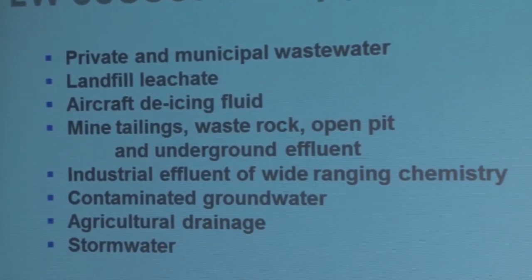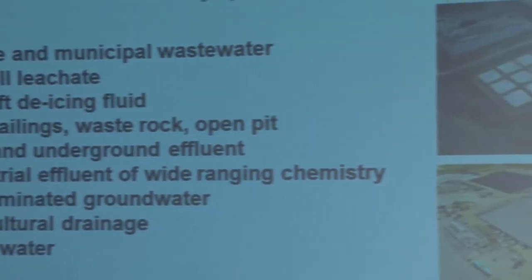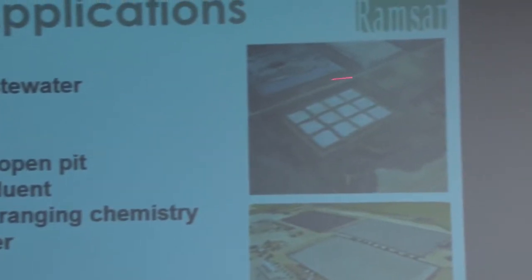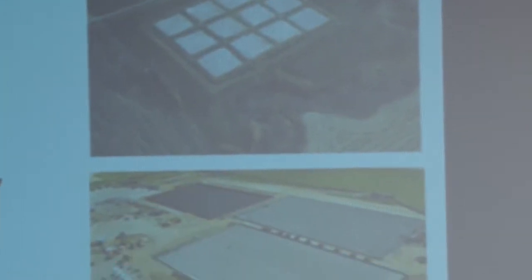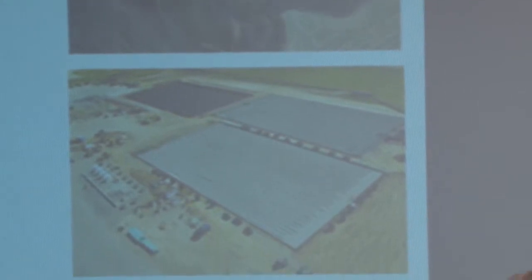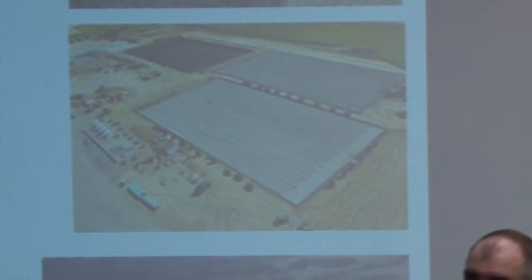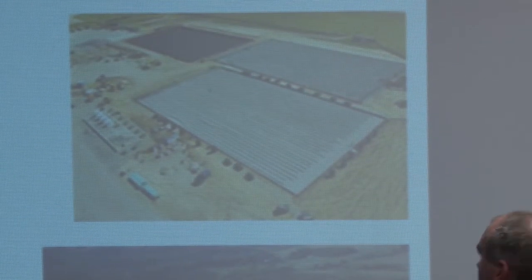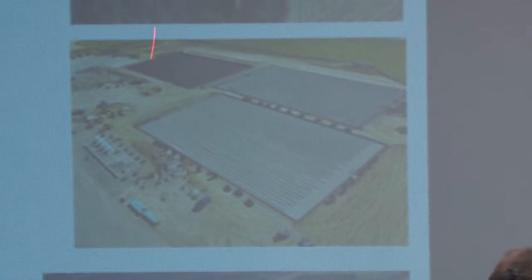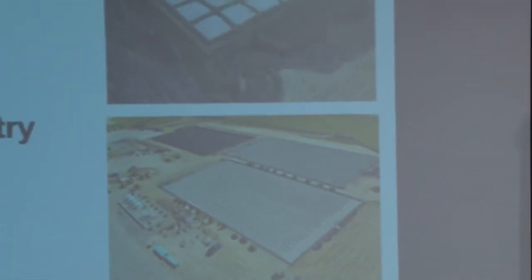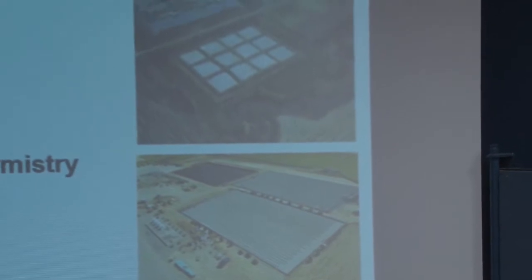So what we have here is a wetland in Edmonton at the Edmonton International Airport. And then here we have a large-scale engineered wetland at the Buffalo Niagara International Airport. Both of these are designed to treat aircraft de-icing fluid, so glycol, ethylene glycol.